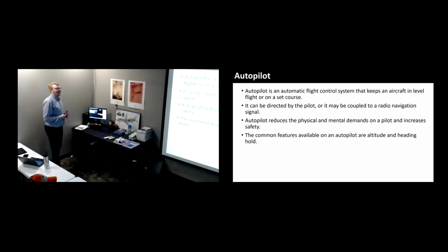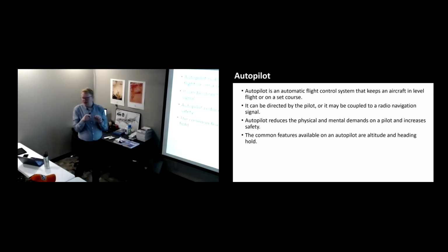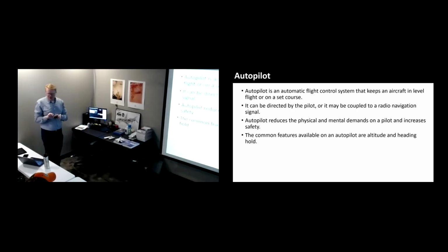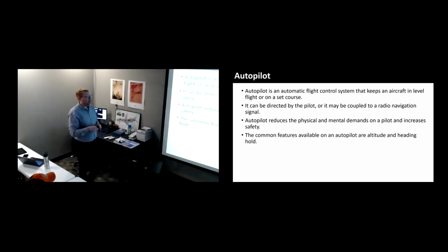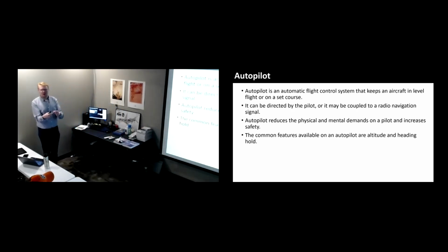All these autopilots work on is they manage the flight controls through mechanical servos. Is everyone familiar with a servo when I say that term? Anyone not familiar? Okay, so imagine a little mechanical motor, about yay big, and that motor is electrically controlled and has a little arm that moves like this. So a little motor, two electric contacts cause it to move. As that moves, it's connected to the control cable and it forces it to move up and down. As it spins, it can allow its movement. So if you turn an autopilot on, that shaft behind there has a pin input to an autopilot servo. And when you turn the autopilot on, your input changes into a servo making that input for the autopilot. So it's just a matter of whether I do it or a mechanical servo.